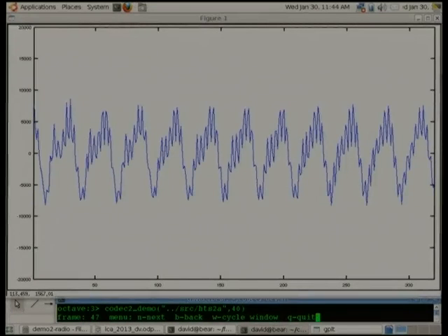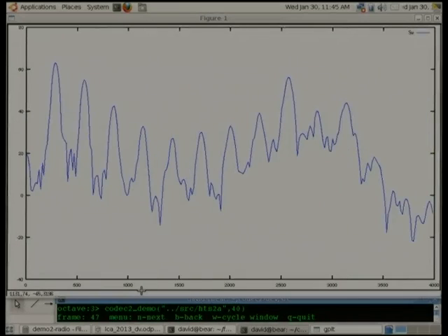Okay, this is a little chunk of sampled speech from a female speaker. She's saying the word "these," and along the bottom here we have a time axis. This is in samples. This is around 40 milliseconds of speech from a female speaker. Now, one thing you can notice is that the signal is evolving slowly across the time, but it does tend to repeat itself. And as you'll see in a moment, anything that repeats itself in the time will also repeat itself in the frequency domain. So this is the spectrum, or a graph of the frequency response of that signal.